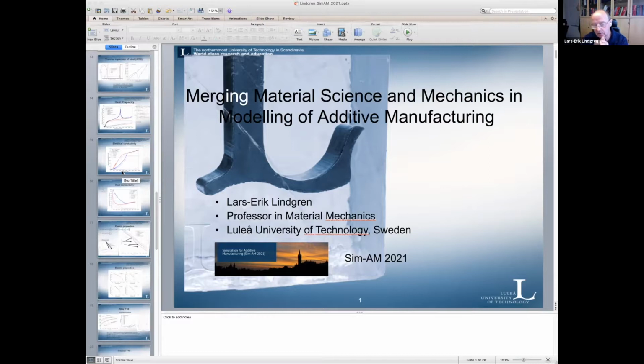Yeah, the precipitate model is of course too limited to handle that kind of detail. It just focuses on the niobium diffusion and the creation of double gamma prime. We don't look at the gamma prime either. So it doesn't know anything about these details. Okay, thanks a lot. And I can just mention that we do have a post-process model for hot cracking, where we look at the molten region between the grains, which is the hot cracking source. And there we look at some segregation in order to predict when it starts to solidify, but that's a pure post-process. Thank you very much.